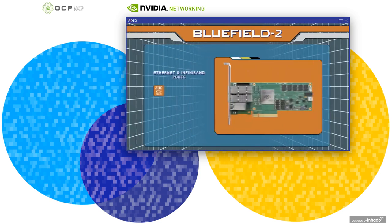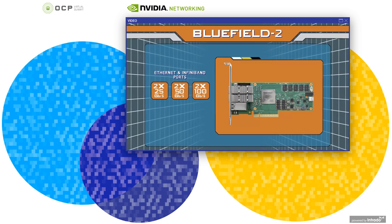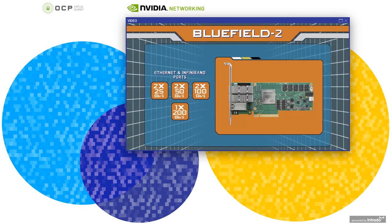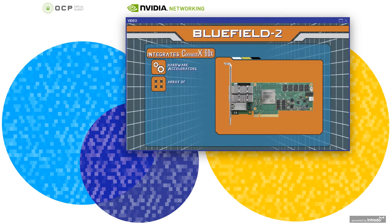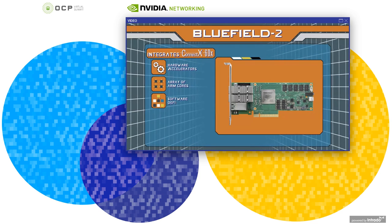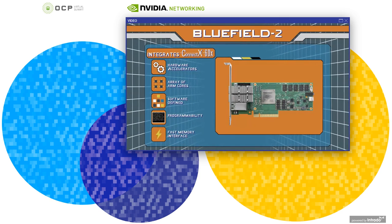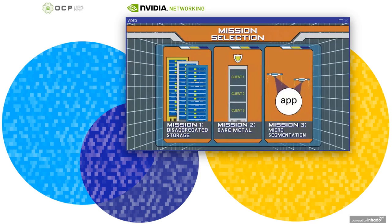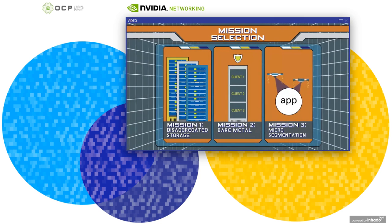BlueField-2 provides 2 ports of 25, 50, or 100 gigabit per second Ethernet and InfiniBand connectivity, or a single 200 gigabit per second port. BlueField-2 Silicon integrates the ConnectX-6 Dx best-in-class network adapter and its hardware accelerators together with an array of ARM cores to enable software-defined networking and storage programmability with a fast memory interface. With all these advanced tools in its arsenal, BlueField-2 is ready to accelerate and secure diverse solutions that can be developed based on it. Here are just a few.